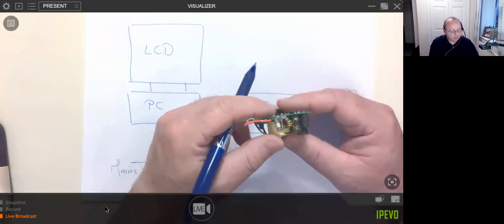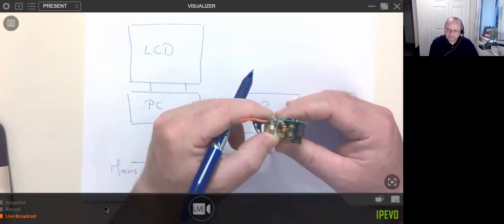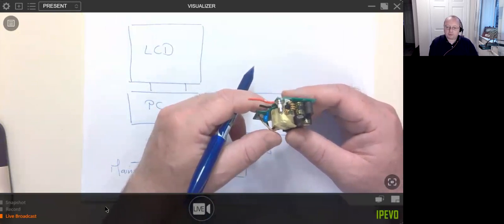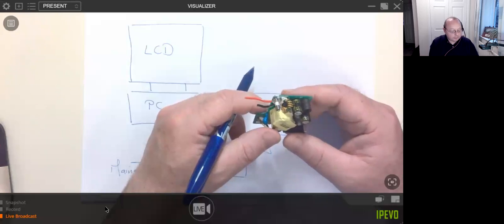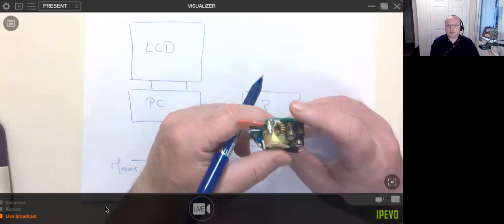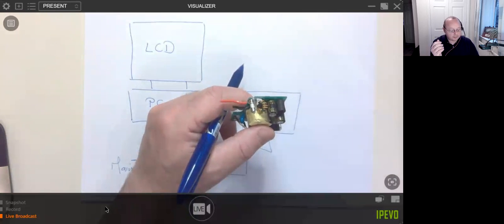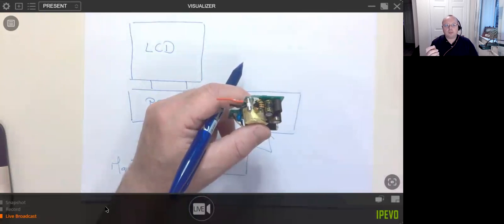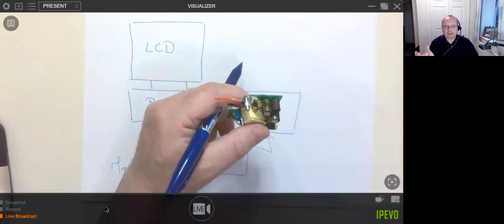And if you're thinking, well, I've got a fuse on it, therefore it's safe, unfortunately under the standard that doesn't actually apply. It has to survive the surge. And of course, the other thing, I'm sure Aga's found this as well, is that one company's interpretation can be different to another's. For example, under a surge test, you're allowed to flinch and then auto recover.